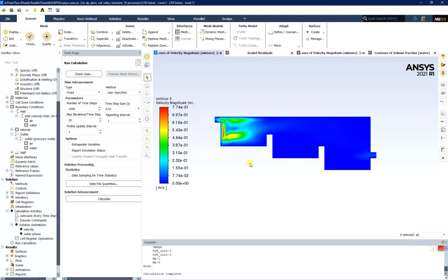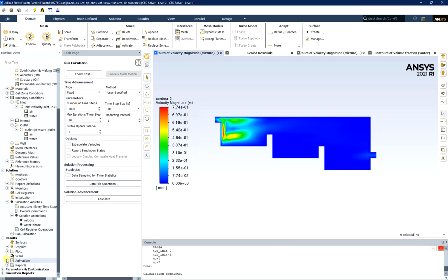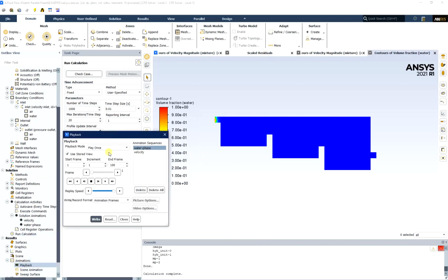All right, so after 11 minutes of calculations, I already reached the end of 1,000 time steps. As I can see over here, if I'm looking at the playback and I'm choosing the waterface, at the end, I just fully fill only half of the first step in my Fishladder. So therefore, I think I may need about 10,000 steps, and I may need about a few hours to run the simulations. In this simulation, I choose my initial velocity is really small, which is 0.1 meter per second.